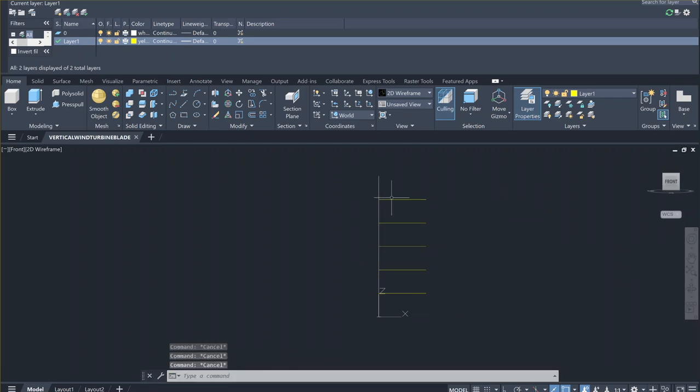Here's the problem that I mentioned to you. Z-axis is showing up, and my UCS is not proper UCS. See, the Z and X is showing only on my screen. This is not a proper UCS to create an ellipse. I have to have X and Y axis showing up so that I can create an ellipse.